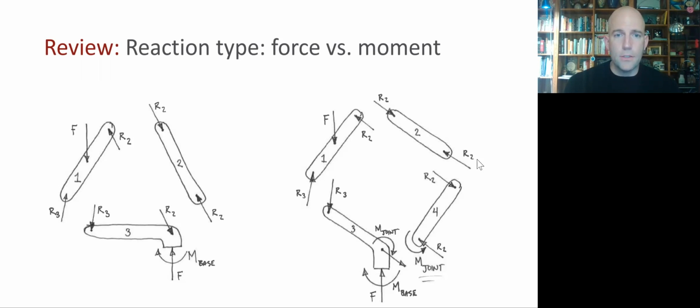On the other hand, if we look at this square scenario, if we do our free body diagrams carefully, we'll see that no matter what kind of assumptions we use, at least one of these joints is going to need to have a moment. If we think about what that means for, say, link 4 here, where you have this reaction force that's basically orthogonal to the link, it's got a big lever arm, so it's going to generate a big moment. That moment has to be reacted out in this joint somehow. What it really means is probably that we're going to have a couple of forces in opposite directions, but their lever arm relative to each other has to be really small because this link is pretty skinny compared to how long it is. So there's going to be a big force multiplier. That means we'll either need some massive hardware in there or we're going to have a weak joint.